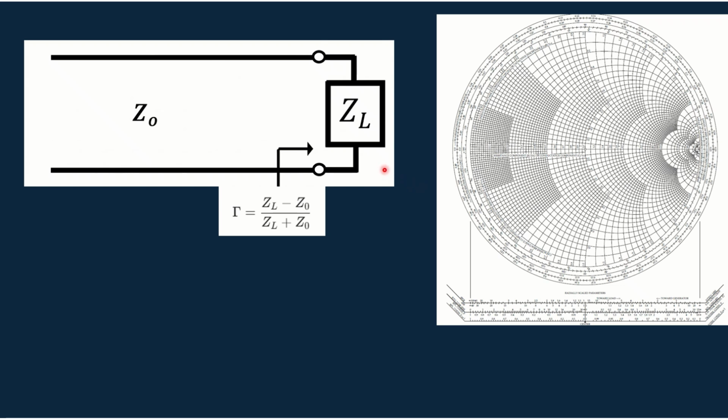In part 2, we have seen that the Smith chart was developed to analyze transmission line problems. In a transmission line, our aim is to have the load impedance the same as the characteristic impedance, because otherwise reflection will happen.